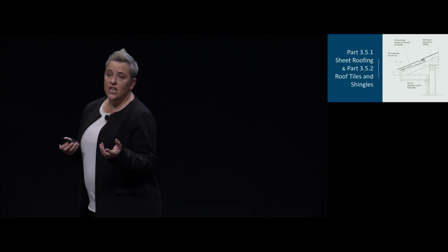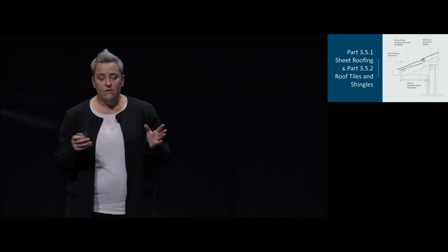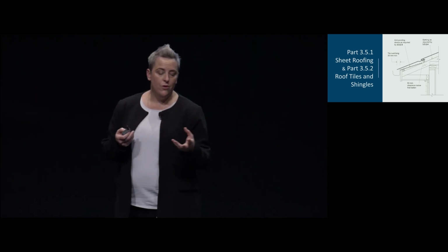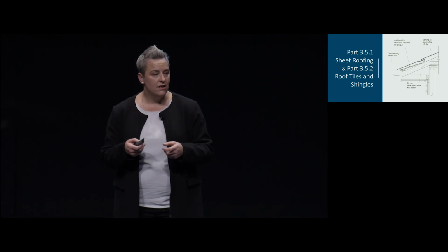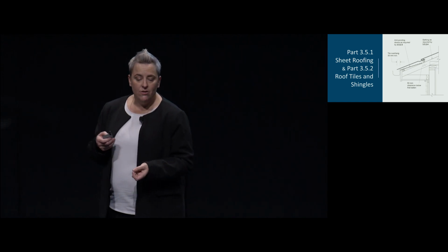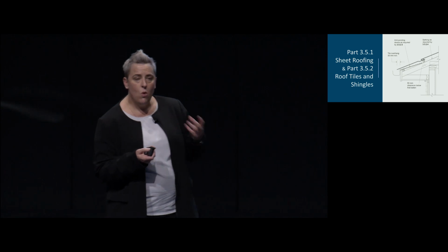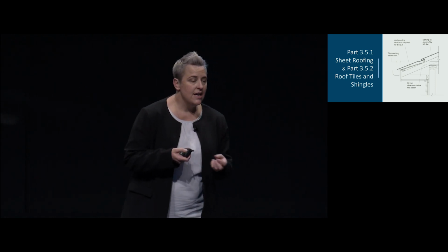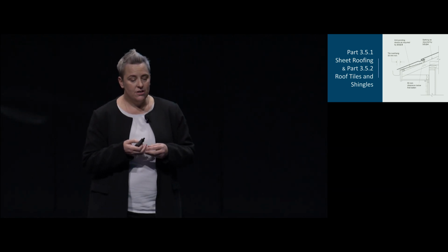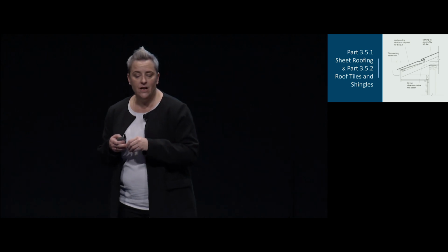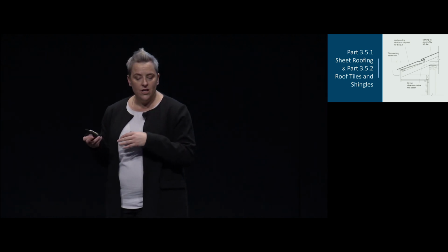The roof tiles and shingles, they've been separated, and the requirements have been detailed and set out to improve the readability once again and reflect improved construction methods. The flashing details for tiled roofs have been expanded significantly to provide details of wall and step flashings and flashings for penetrations. So the figure up on the screen shows the acceptable flashing configurations that have been included in the provisions.